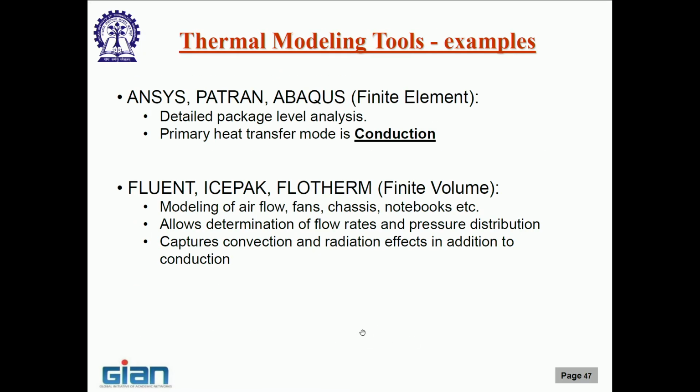Okay. So, what are thermal modeling tools that we normally use? See, there are two types of models that you can do. One is just a finite element based, where the primary heat transfer mode is conduction. So, that example that we were talking about, the die, then the TIM, etc., even including spreading and all, I can do a pure conduction mode, because I am not modeling flow. In terms of solving differential equations, I am only solving the energy equation, and that too just with conduction terms, no flow. So, that is sometimes used.